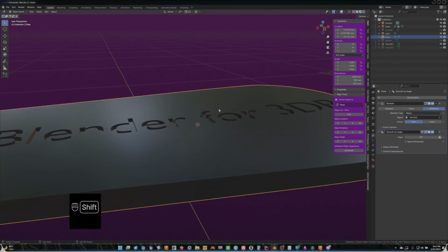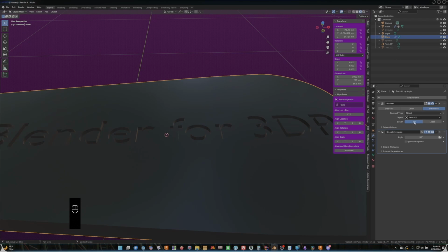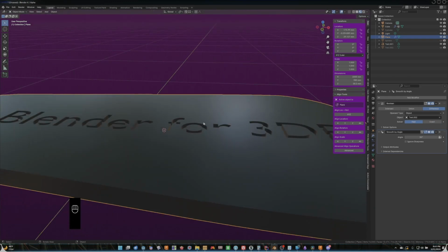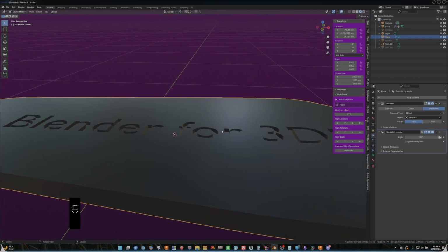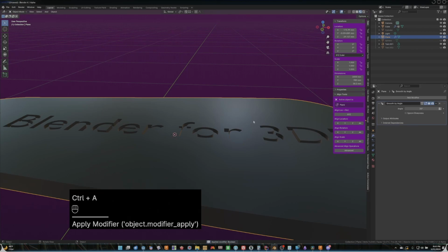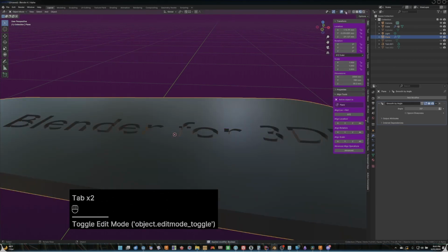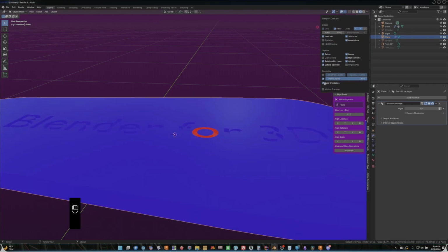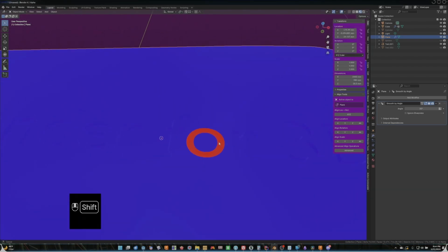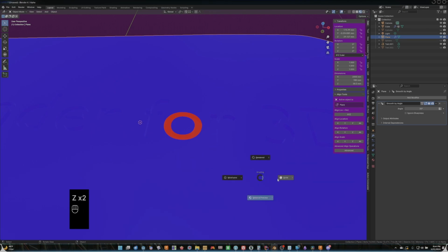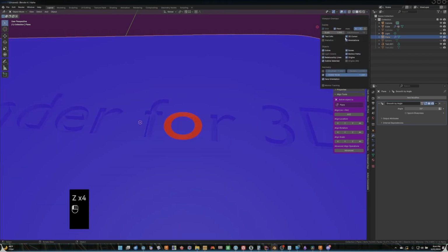However, if you do have inverted normals, a quick way of overcoming that is just by switching to the fast solver. If you're going for precision, you can leave it on exact, but that's one way to overcome that issue really quickly. Unfortunately, I think if we apply this, our normals may have issues. I'm going to just turn on face orientation. Yes. So the normals now have issues, so they won't show up properly whenever you're trying to do different operations.